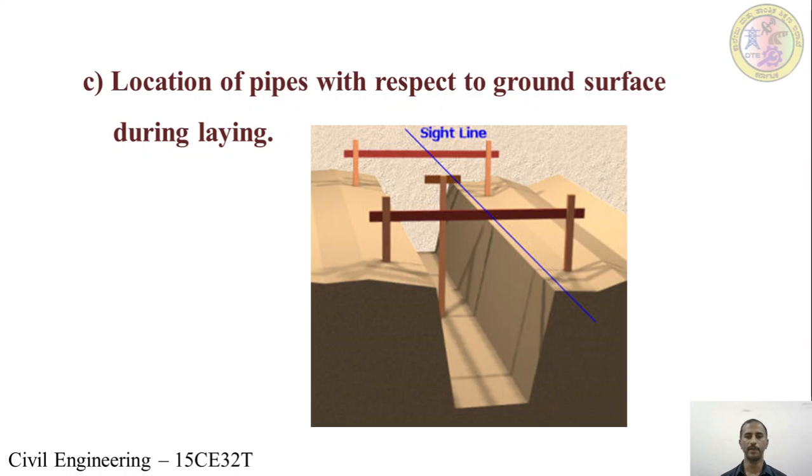If the pipeline crosses a waterway, a concrete column is provided immediately after the concrete block at a distance of 1.5 meter on either side of the waterway. Flanged joints are provided at 4 to 6 meter interval, and it is noted that these flanged joints should be symmetrical on either side of the supports.